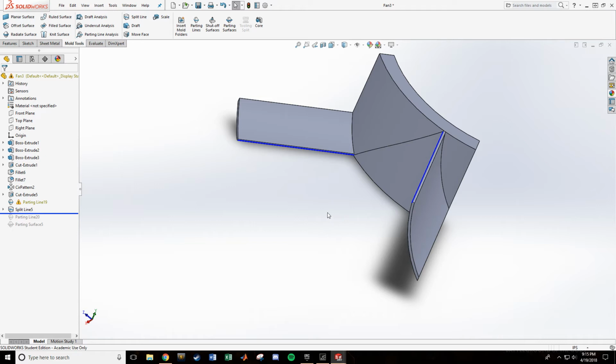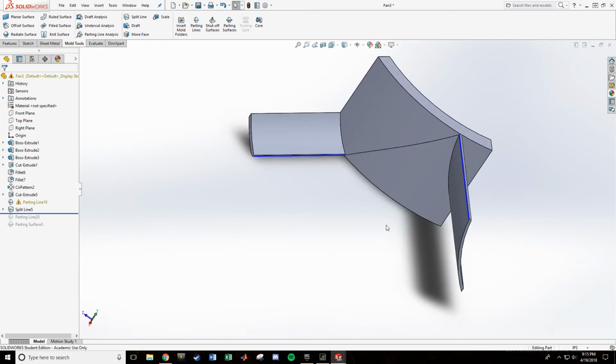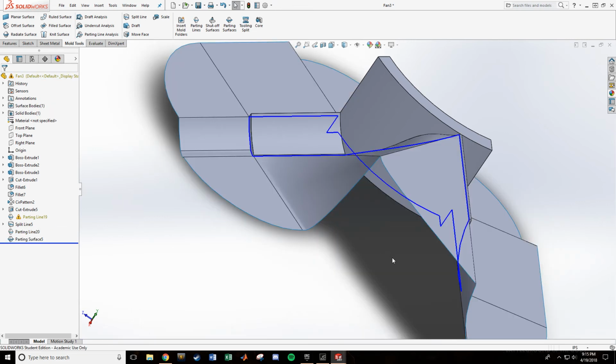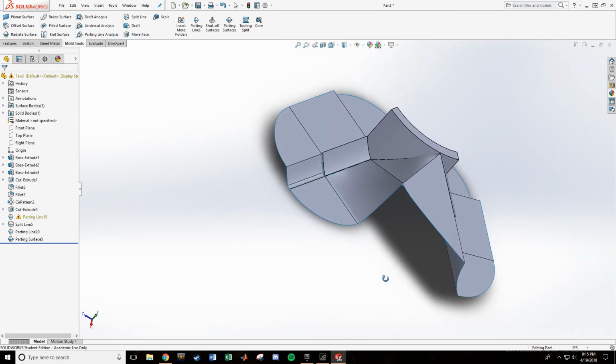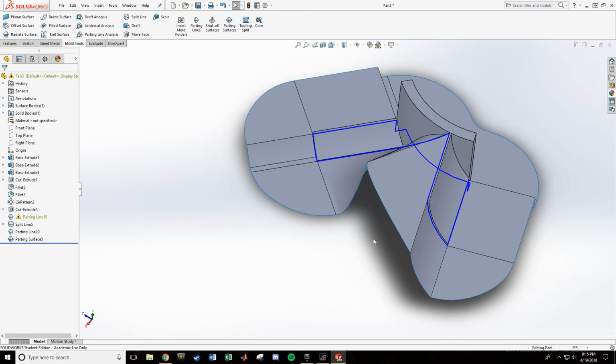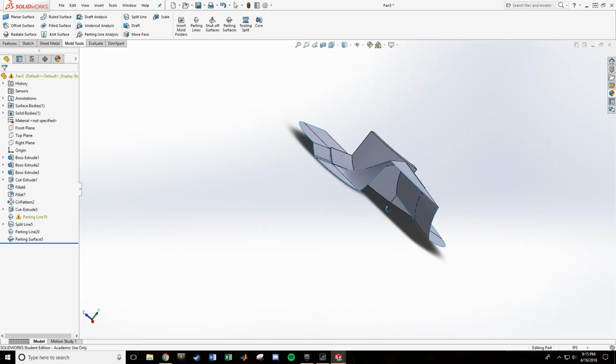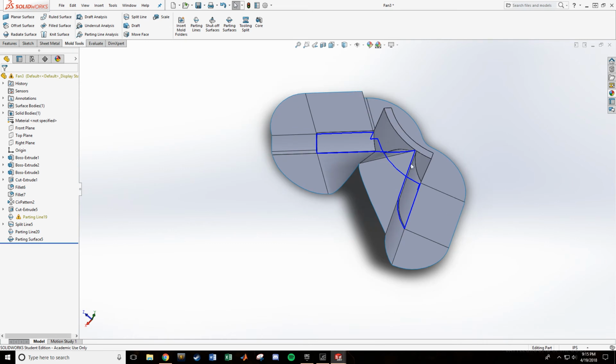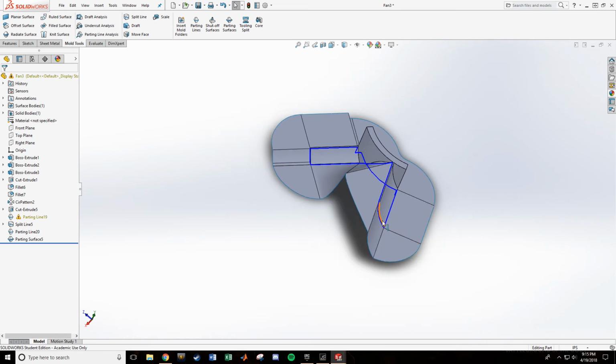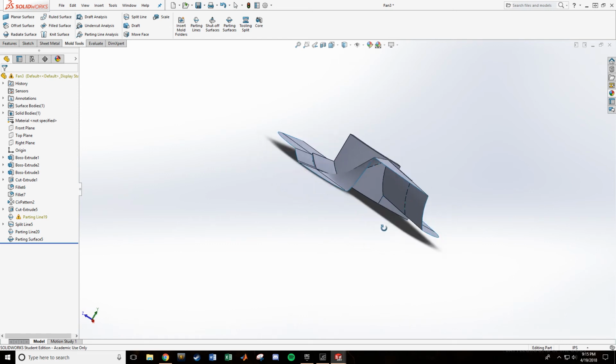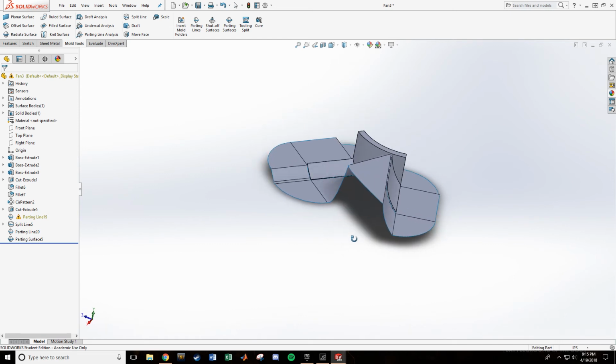In theory, SOLIDWORKS should connect these new planes together in order to make a sort of puzzle piece design for the two halves of the mold. However, after 2 weeks of troubleshooting this method, we're still unable to create a successful tooling split. And we don't know if that is something dealing within SOLIDWORKS with it being too complicated of a geometry. It basically tells us that it's unable to mesh knit the surfaces together, meaning it can't complete the loop and create that tooling split. We don't know if we're missing just something small or if it's something deeper within SOLIDWORKS that's causing this error.